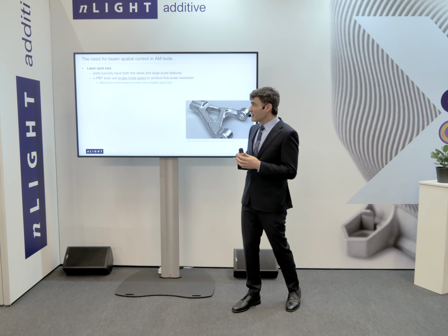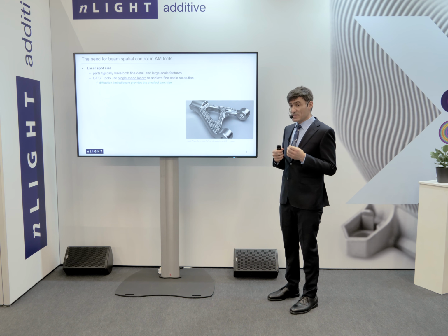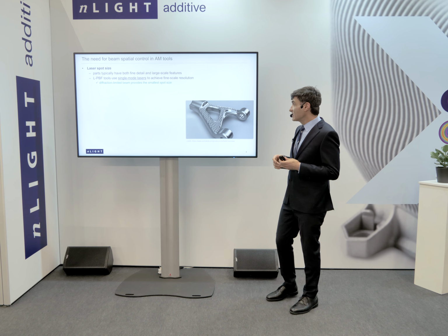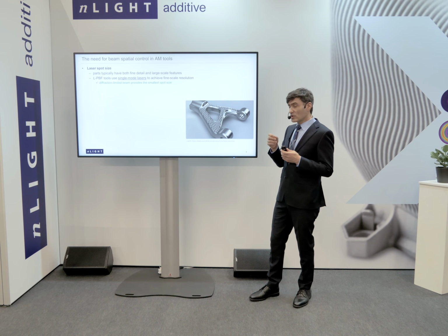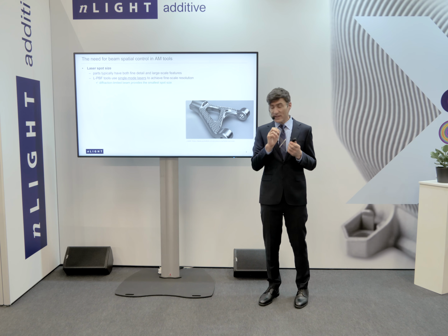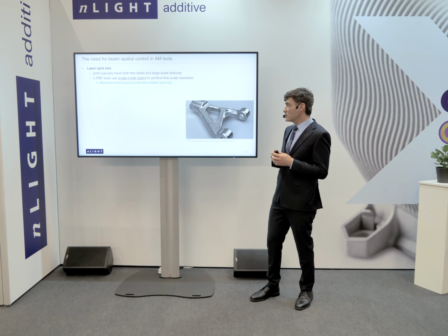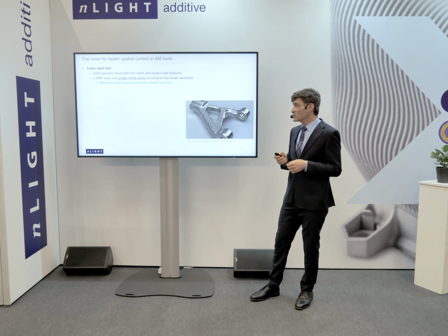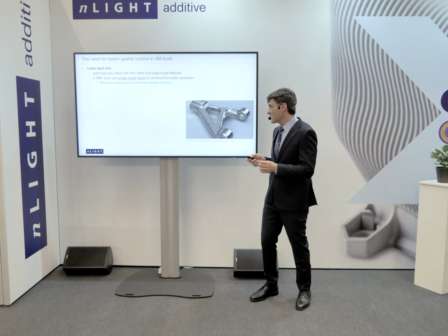But what about additive manufacturing? Well, the need for spatial control of the beam is really clear here. In typical additive parts, you have both fine detail and larger scale features. In order to be able to print the small scale fine features, most laser powder bed fusion tools use single mode lasers, which give you a diffraction limited beam, which gives you the smallest size so that you can write